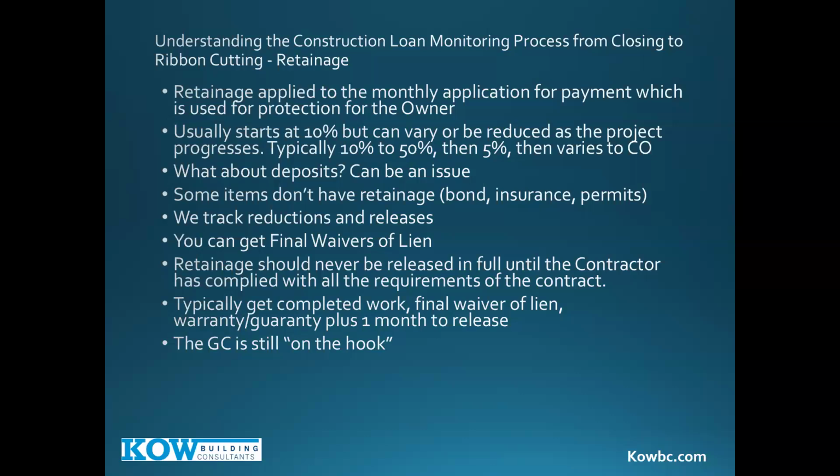Guess what? If there was no retainage on that framer, that would have been a harder callback probably. And they came back, they fixed it. Then when everything was signed off, all the framing was accepted, everything was done, it was fully released. So that's a good example of why a retainage is used. From a GC standpoint, it's used as well, like we talked about earlier, and it gives you that cushion just like that framer, but the overall project.